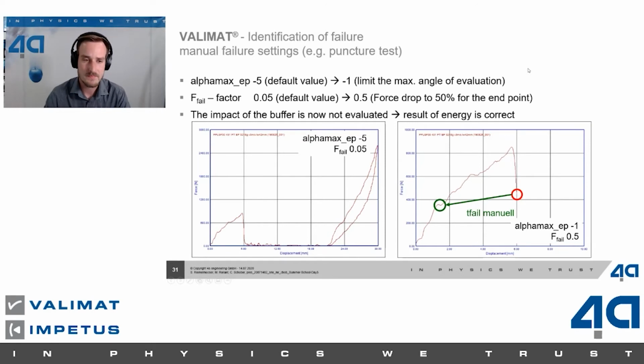When we see this slide, on the left side we have a force displacement diagram, and this diagram shows you a puncture test of a fiber reinforced plastic, and it's a quite strange result, I think. And what can we see here? We see one drop in this area, and we see one big force peak in this area.